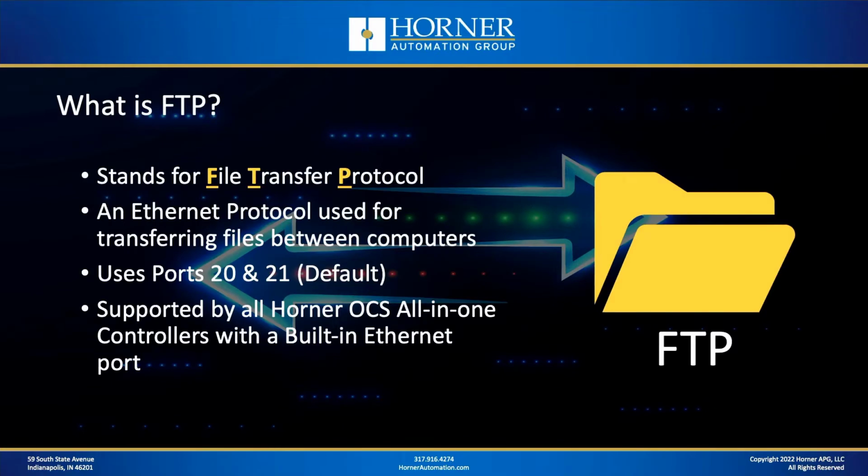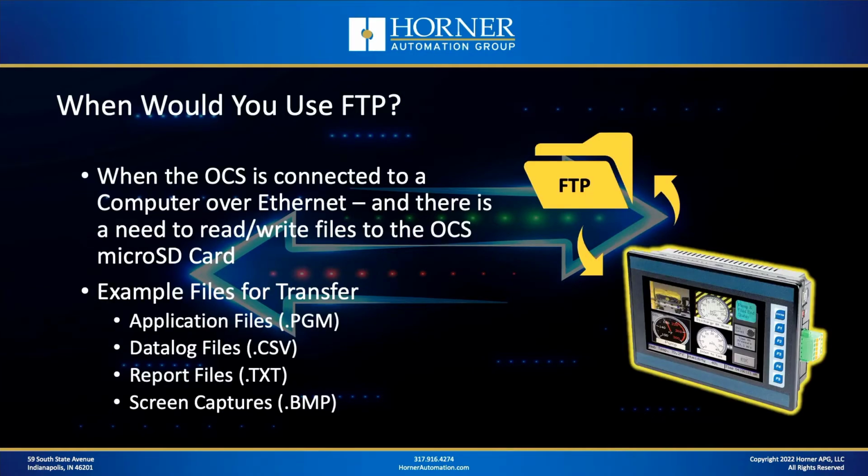So what is FTP? Well, most of you already know FTP stands for File Transfer Protocol. It's an Ethernet-based protocol used for transferring files between computers, from computer to machine, and vice versa. Now, from an Ethernet port standpoint, it uses ports 20 and 21, and it's supported by all Horner OCS All-in-one Controllers with a built-in Ethernet port. And these days, that's just about everything we sell, except for the X2 entry-level micro OCS. Every other product either comes with Ethernet standard, or in the case of XLE and XLT, it's an option at no additional cost.